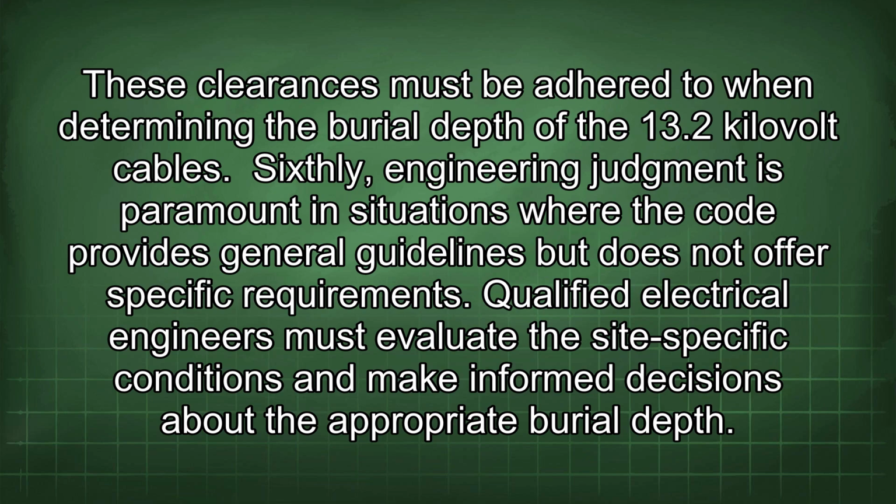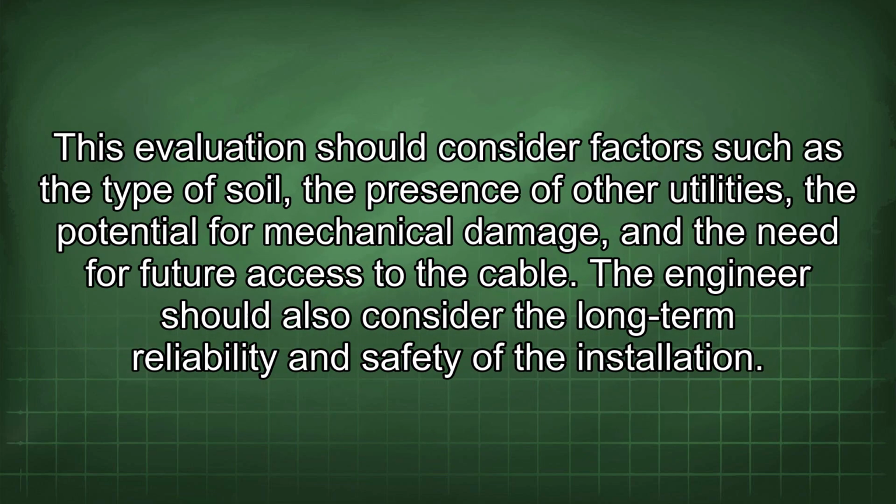Sixthly, engineering judgment is paramount in situations where the code provides general guidelines but does not offer specific requirements. Qualified electrical engineers must evaluate the site-specific conditions and make informed decisions about the appropriate burial depth. This evaluation should consider factors such as the type of soil, the presence of other utilities, the potential for mechanical damage, and the need for future access to the cable. The engineer should also consider the long-term reliability and safety of the installation.